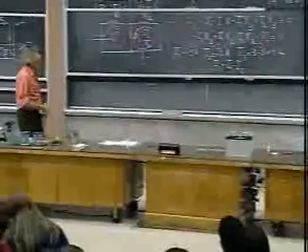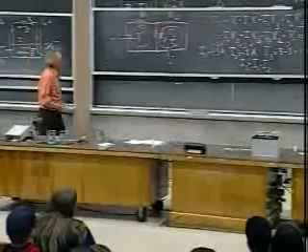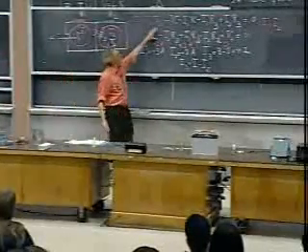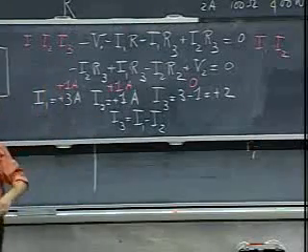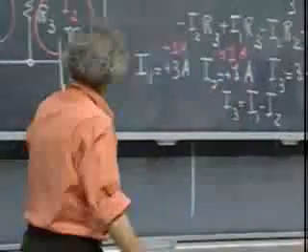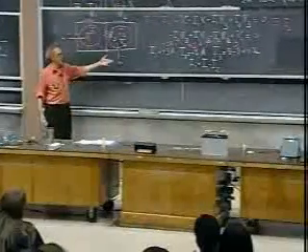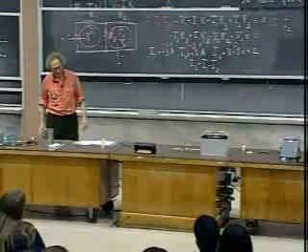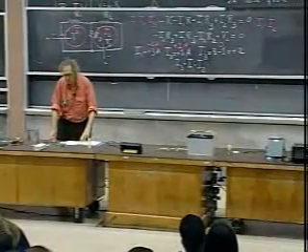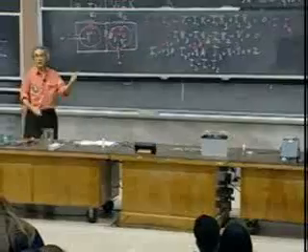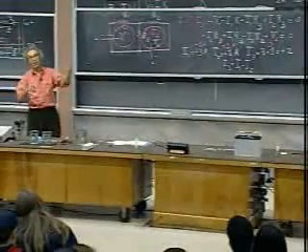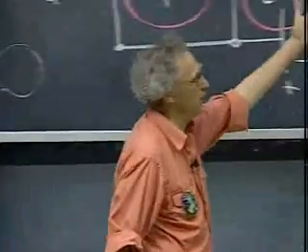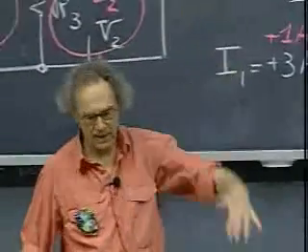I know some of you don't like it. It's fine. The reason why I like it is I always end up, in this case, with two equations with two unknowns. I solve for I1, I solve for I2, and then the third one comes out in a natural way by just thinking, one current goes in this direction and the other goes in that direction. But if you prefer the method that the book will present to you, you get 3 equations with 3 unknowns, and you get I1, I2, and I3. Right at the start, you get an I3. You see, I don't even start off with an I3. It's not there. It comes in later. So the choice is yours.